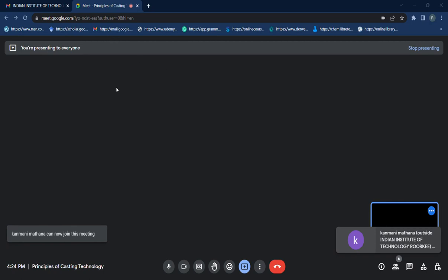So your total volume of the riser which you would need to fill will be the sum of this and this one which we calculated. I can write it as VR final, your total, will be volume of your appendage plus volume of the riser which we calculated.